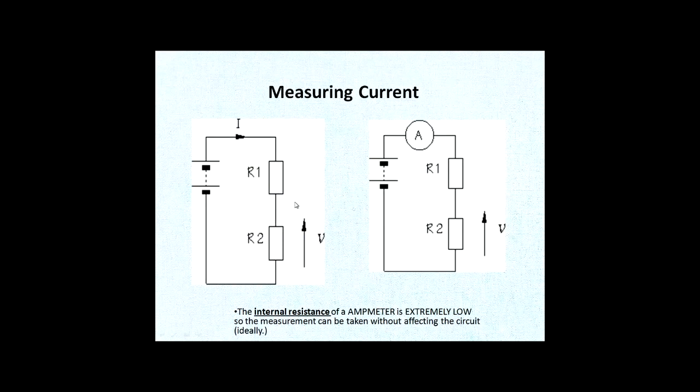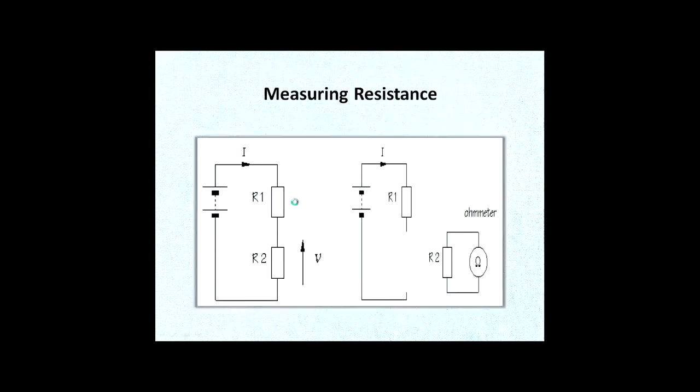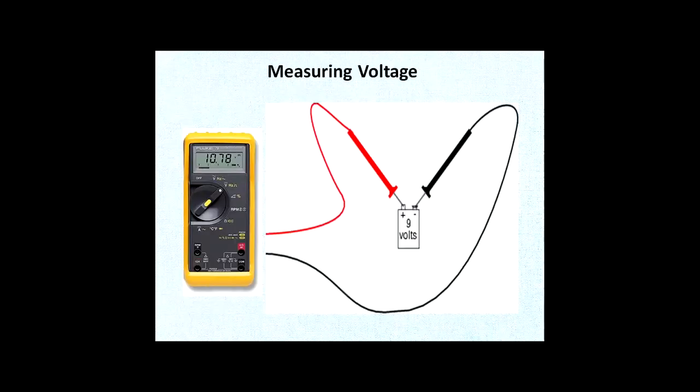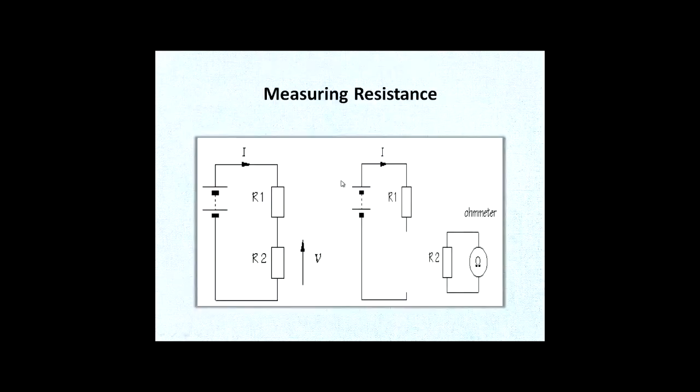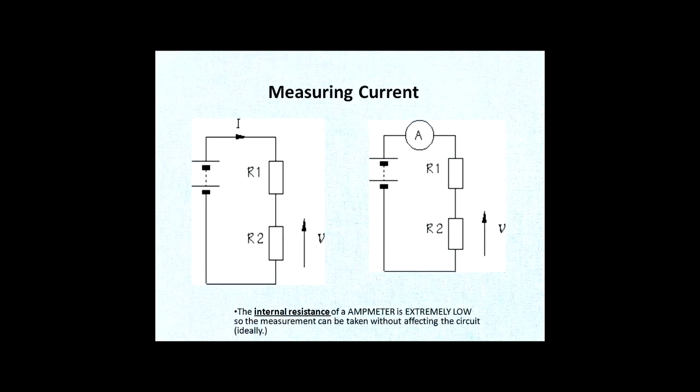Okay, so remember when we were measuring the voltage, we would connect across this resistor, we would connect the voltmeter in parallel with the load. Now, the amp meter, we're going to connect in series. Okay, so here's the amp meter.